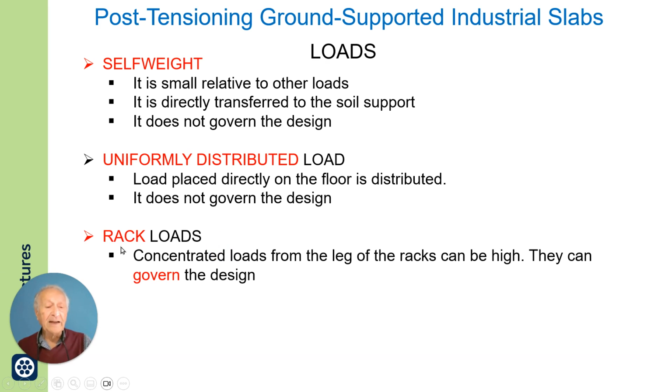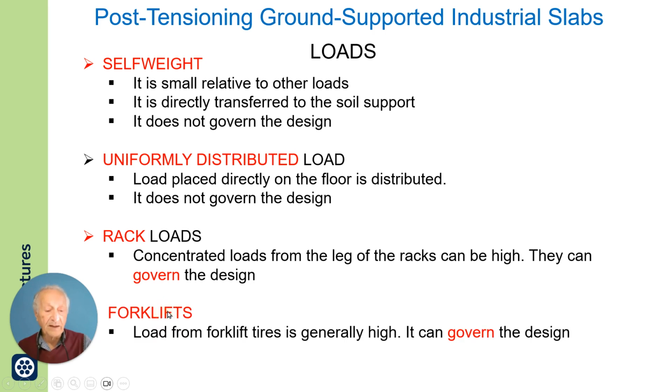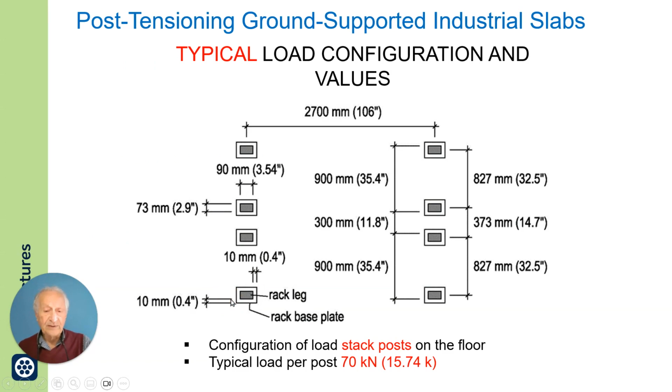Forklift and rack loads, where the material is stored, these are concentrated loads from the leg of the racks. These could be high. They can govern the design. Forklift tires can also govern your design. So essentially we concentrate on the load from the racks and from forklift.